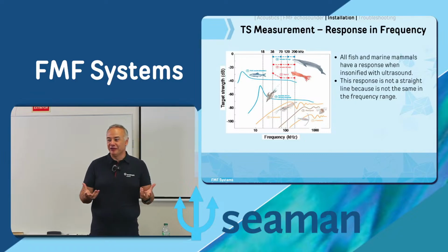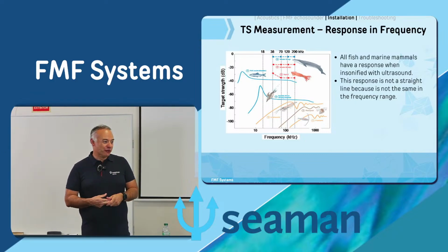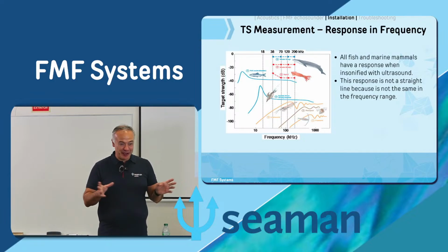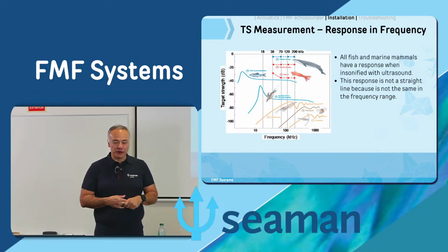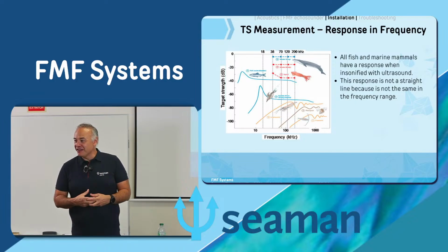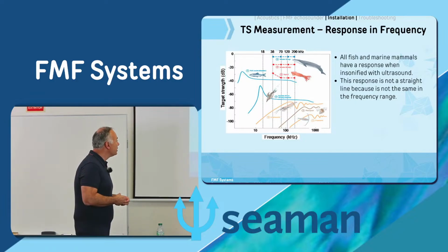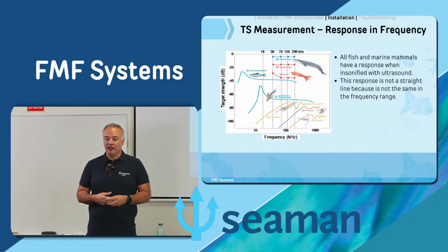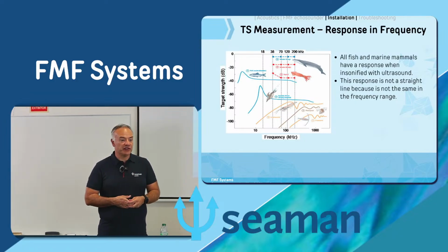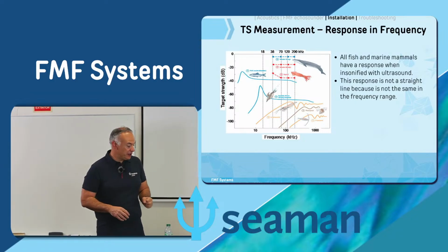Even though we are not fishermen, we look at echosounder screens every day. So when you do that, you train your brain to read the information on the screen. You see the shape, you see the depth of the trace, and you understand, and you can identify species. And when you have identified it, you apply the right formula to measure it.